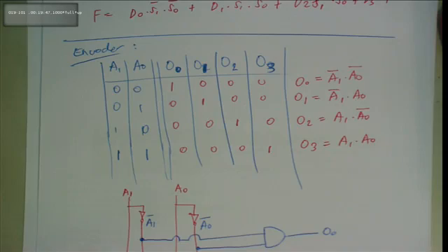We gave this problem already on Monday. Going from big, let's say if you've got a 3 to 8 decoder, or if you've got an 8 to 1 multiplexer, and you want to just build a 2 to 1 multiplexer or a 4 to 1 multiplexer, all you've got to do is just tie one control line, one selector line to ground, the most significant one, right? And same thing goes for a decoder.